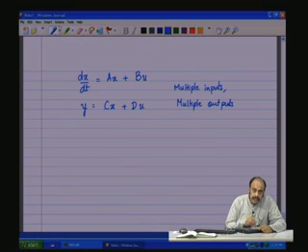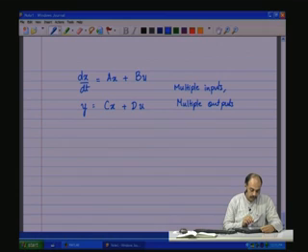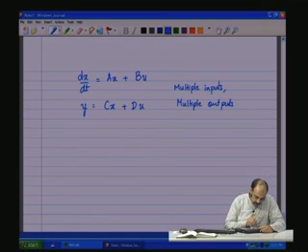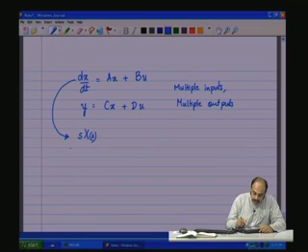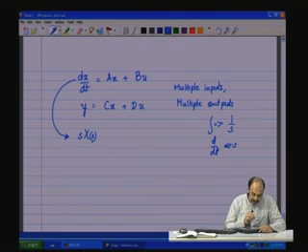Now, how do we obtain the transfer function for any circuit where you have the equations given like this? The transfer function is obtained in the following manner. Taking this dynamic equation, we have s X(s), because when we say integral is replaceable by 1 by s, d by dt is replaceable by s when the initial conditions are 0.